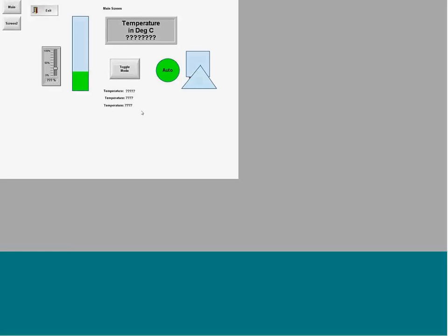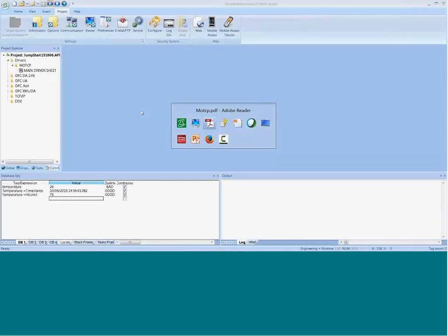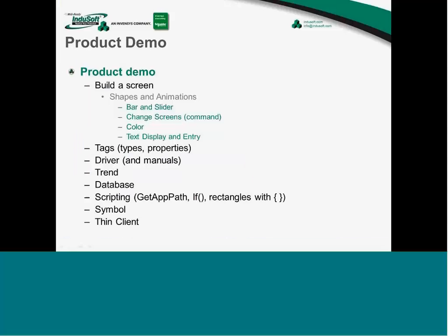That's so we don't show an invalid value. We show question marks to let the operator know that's not a real good value and it's got bad quality, so don't show the wrong value. That could lead to some dangerous situations. There are some industries that might want to show the last value as opposed to no value at all. That might be a reason why you do that, so you don't check that checkbox. So that's why that works that way.